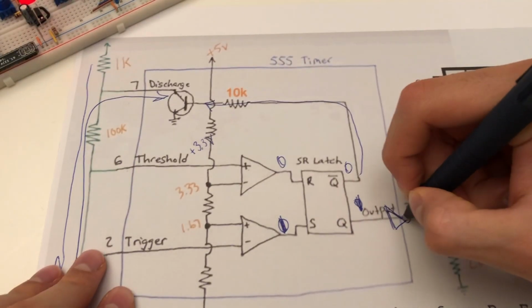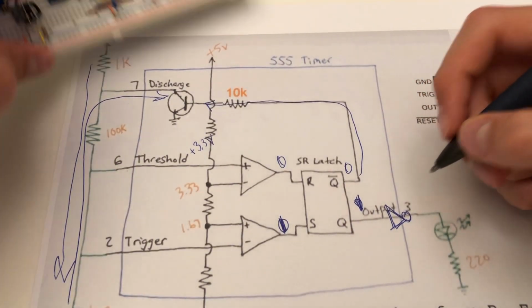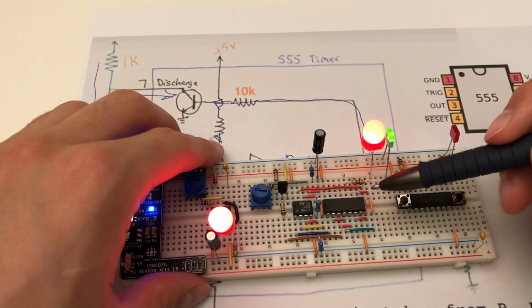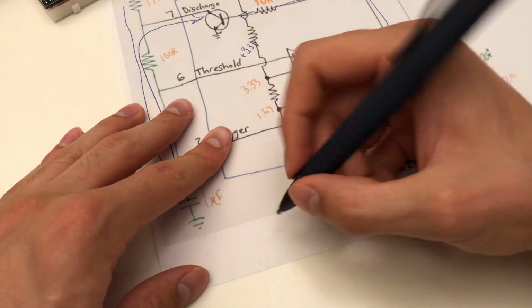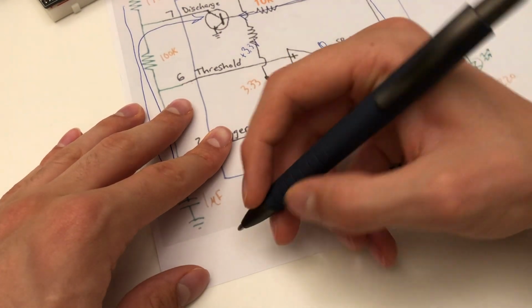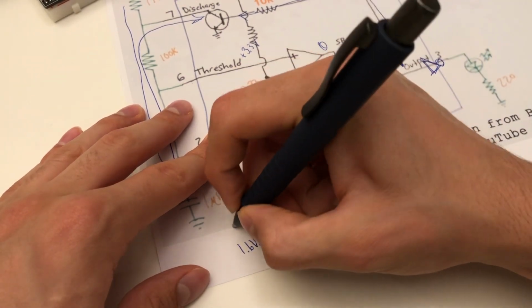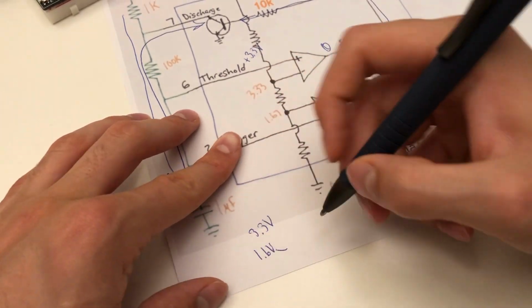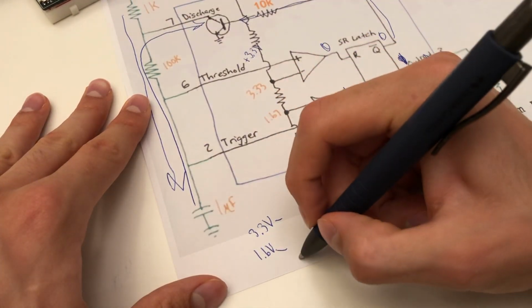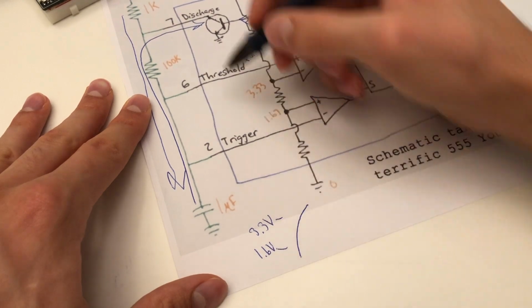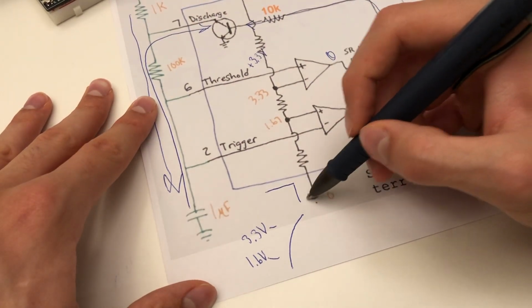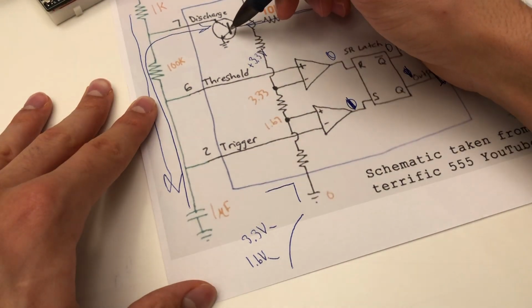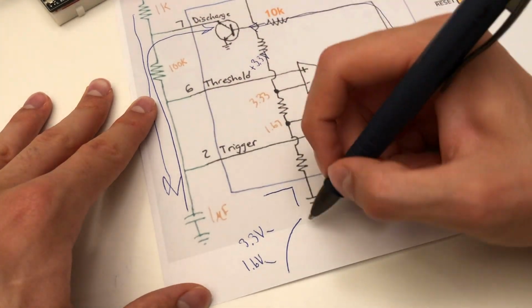At the end in the deconstructed circuit, a NOT gate made out of NOR gates is placed to just rectify the output. So let's draw this capacitor charging and discharging. So 1.6 volts, and let's see, this is 3.3 volts. The capacitor starts to charge, as we know, and then as soon as it reaches above 3.3, this resets the latch so the output goes low, and then that connects to the transistor and the capacitor starts discharging.